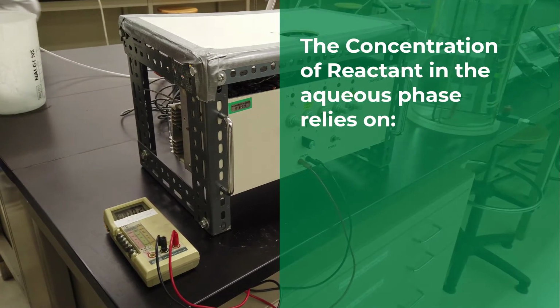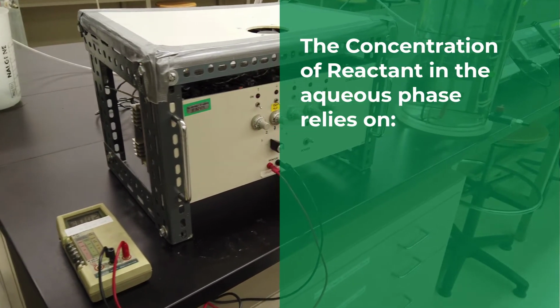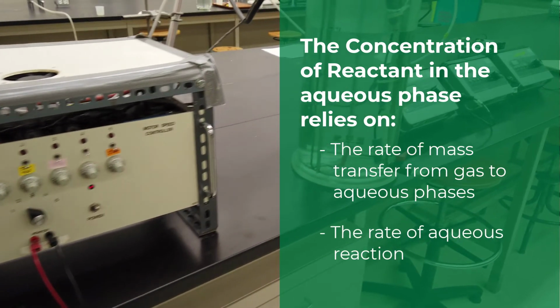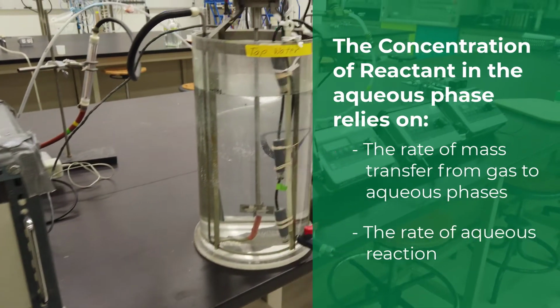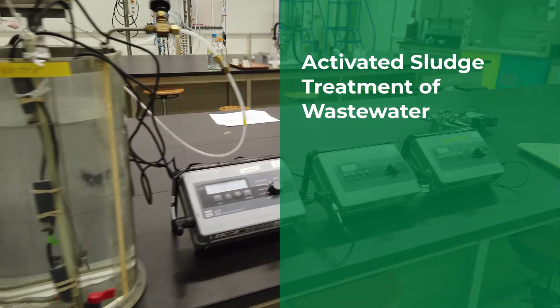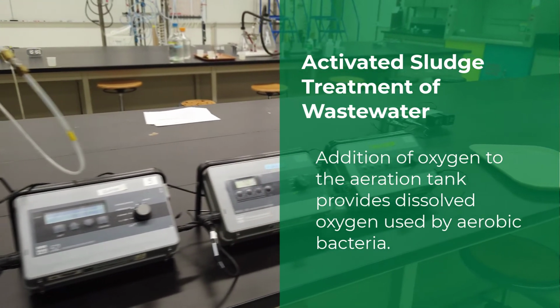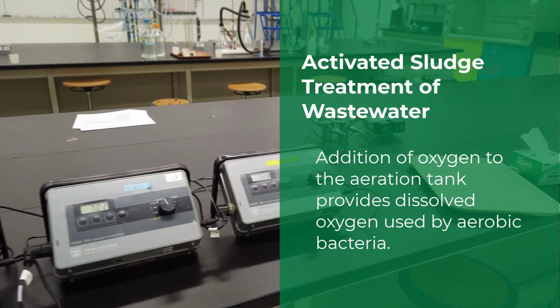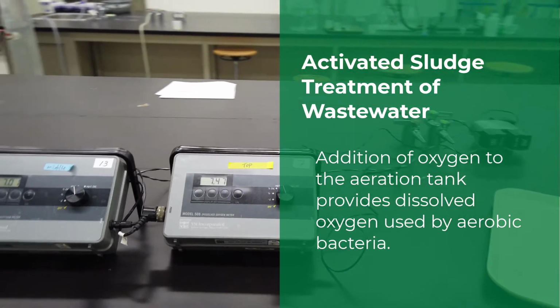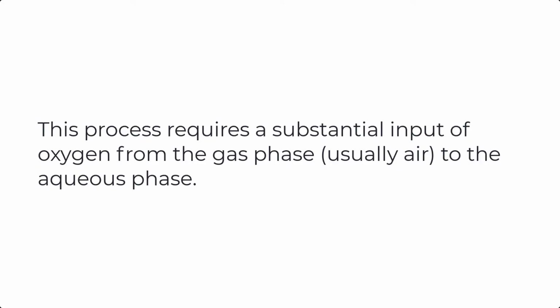The concentration of the reactant in the aqueous phase relies on the rate of mass transfer from the gas phase to the aqueous phase and on the rate of the aqueous reaction. For example, in the case of activated sludge treatment of wastewater, the addition of oxygen to the aeration tank provides dissolved oxygen used by aerobic bacteria to biooxidize soluble organic compounds to derive energy and produce biomass. This process requires substantial input of oxygen from the gas phase, usually air, to the aqueous phase.